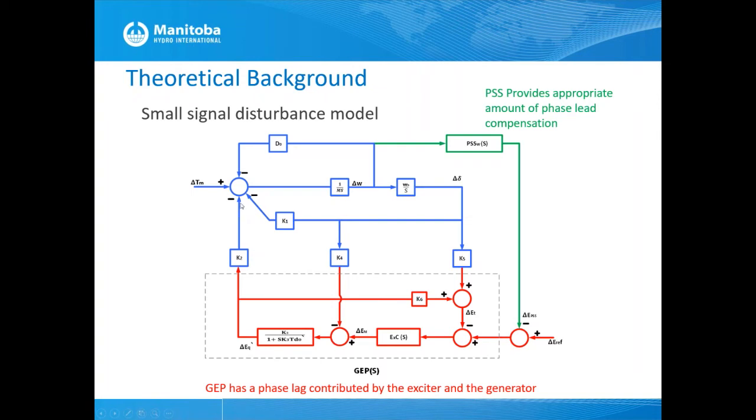And this is the torque going into the electrical component of electrical torque in the air gap. So there are actually a number of torque components. Let's identify them. Here, this is the torque component coming from the governor and turbine, mechanical torque. And here you can see this torque component is proportional to delta omega. So this is the mechanical damping available in the generator.